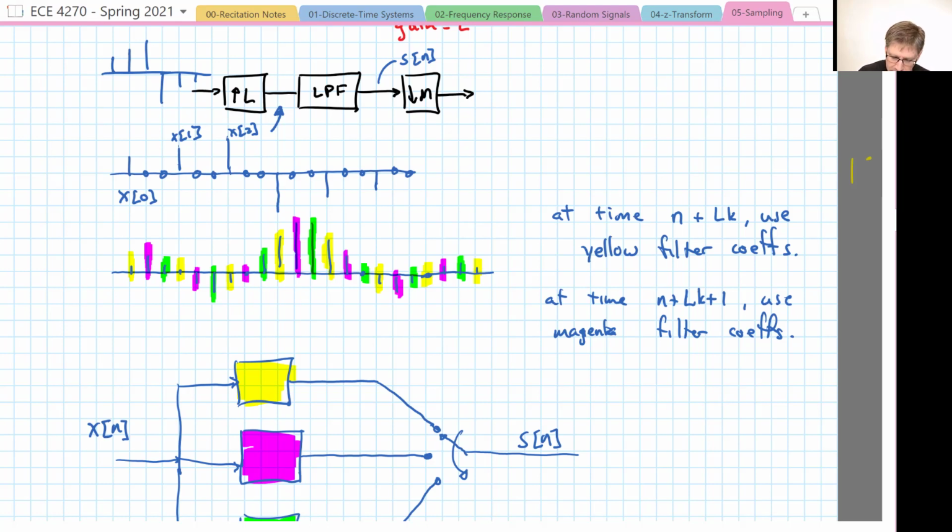So here, we will now essentially move this by M steps each time. And we have shorter filters that we're operating on, and we end up now operating at a much slower computation rate. And in fact, polyphase filtering can be extremely efficient, and even more efficient than, say, using simple IIR filters. Plus you have the advantage that you can have FIR filters, which can have linear phase and nicely designed characteristics. We'll be talking more about that later.